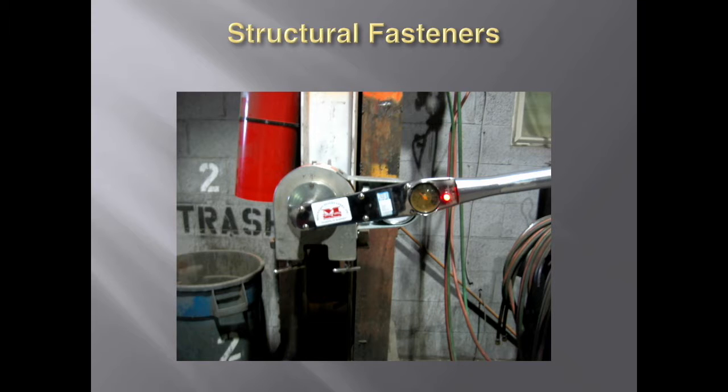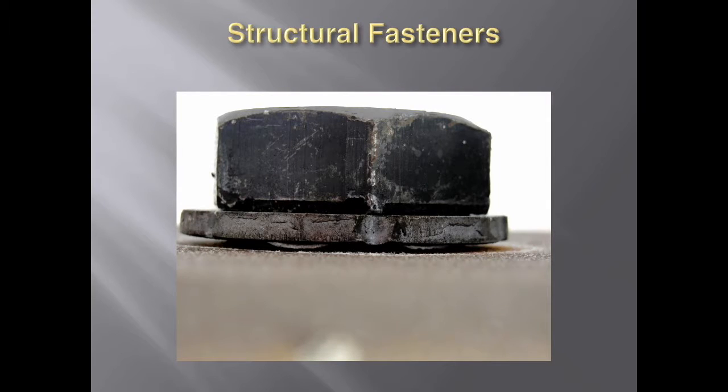This is also a good thing to go through with the bolting crews themselves. That way we can catch them right at the very beginning to make sure that all the bolts are going in correctly. Because we use the DTIs on all of our bolts. We don't use TC bolts. We use DTIs. As you can see, this one is actually upside down.